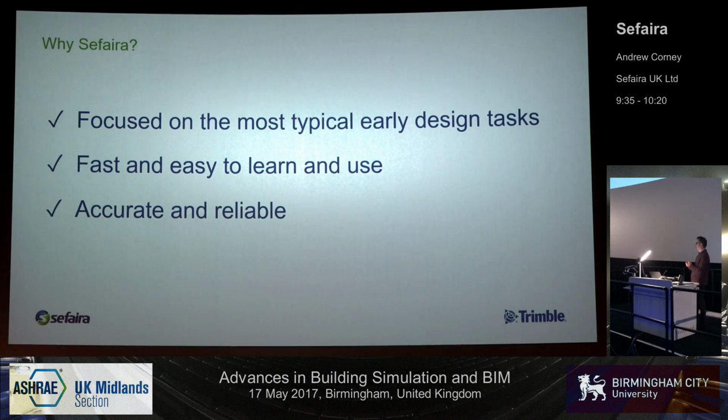Okay, we have time for one quick question. Yes. I was curious about the way you do the zoning. So in SketchUp, there's actually no object that is to base that on. So what is the process for defining the zones in SketchUp? Yes, thank you for the question. The question was how do we do the zoning in SketchUp? Essentially we draw lines on the floor plate. If you just simply draw lines on the floor plate to denote where the zones are, we use that to define the zone boundaries. So yeah, it's pretty straightforward.